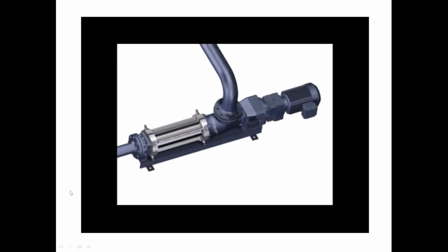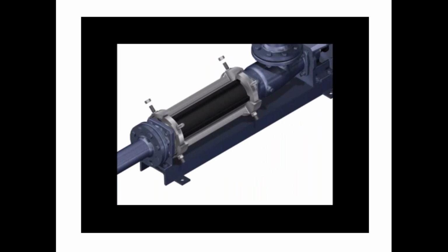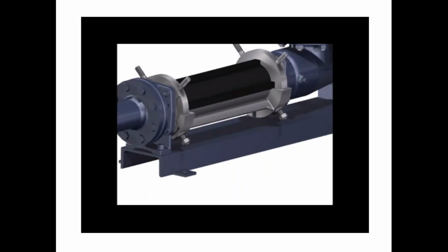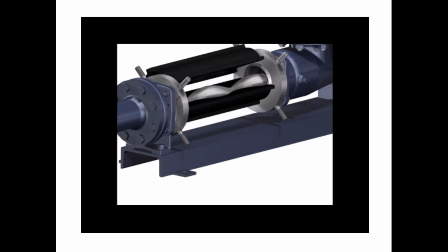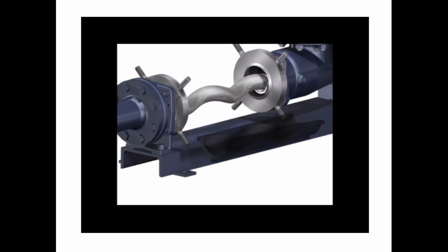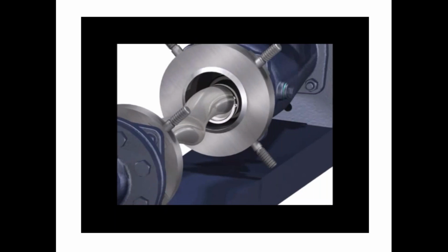Seepex broke into the market with a pump called the SCT, Smart Conveying Technology. The SCT, as you can see in the video, is maintained in place with 4 metal adjustment plates. Those plates can be loosened or tightened depending on what you want the pump to perform. The stator would split in half, hence the SCT split stator, which exposed the rotor, which with a pair of circlip pliers could be pulled out similar to a plug and play action.